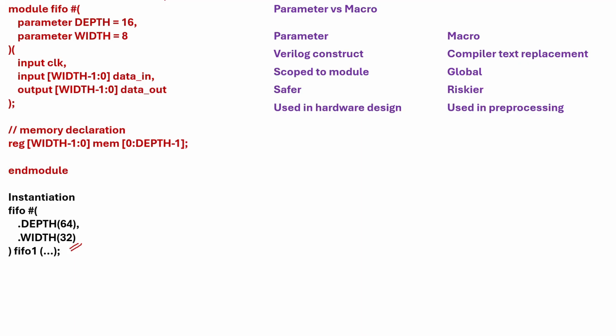See, what are the Verilog constructs? So those are the compiler directives, like parameters versus macros. Parameters are always taken as Verilog constructs. Constructs means some parameter names and keywords you are considering, right? All these are related to constructs. And here we are taking compiler directives, that means tick define, tick include, tick not defined, all these things.